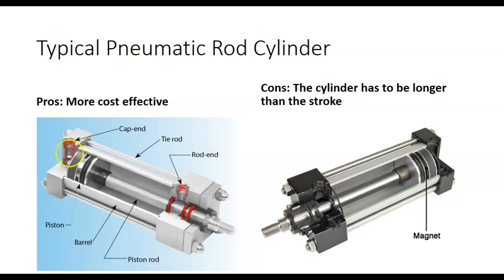And then, of course, we have the piston. Now, in pneumatics, the piston will probably have a magnet on it, and you can actually see it on this one. They're basically the same. And then what we can do is mount a Hall effect or a magnetic reed switch out there and detect the position. Usually we only look for when it's fully extended and fully retracted.